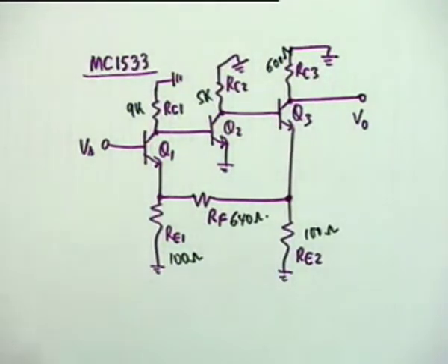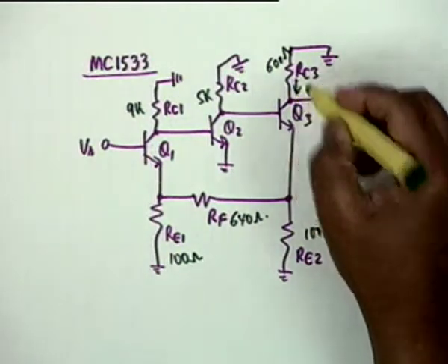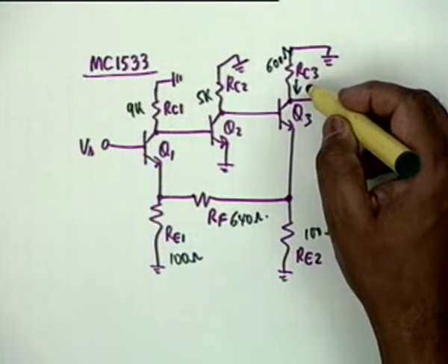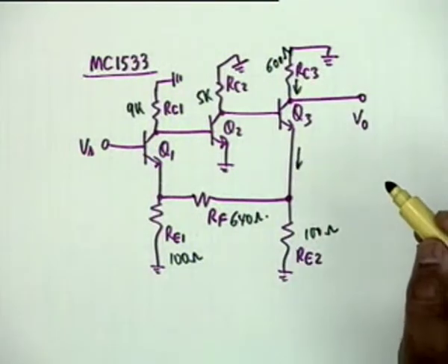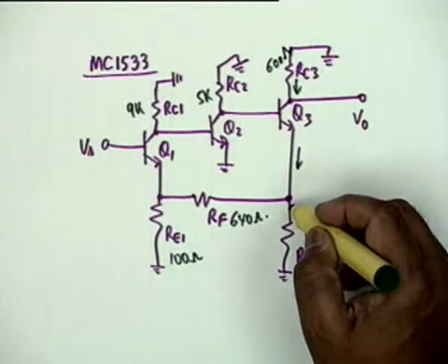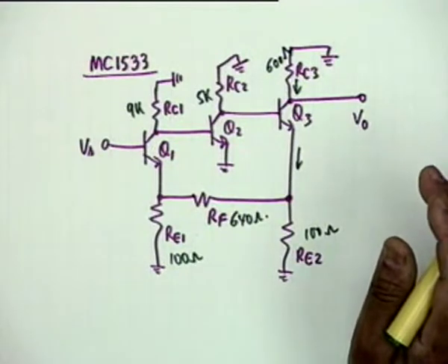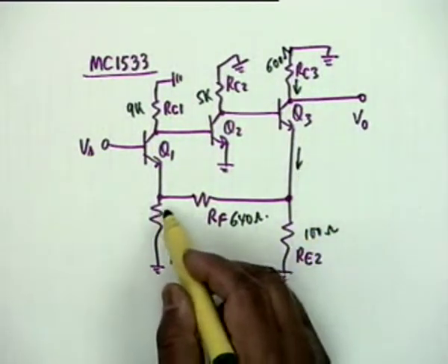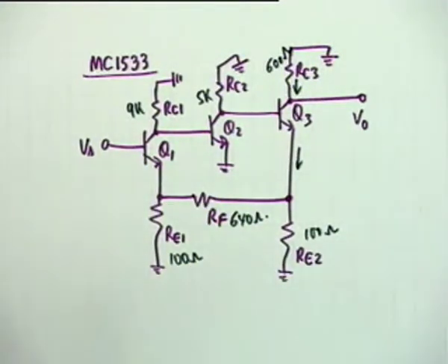Now, why am I saying that this is a series? You see the current here, the output current, approximately the same current flows here, and therefore this is a current sampling. Okay, this also we are acquainted with. This is a very standard method, particularly in IC configurations. So it's a current sampling, and obviously there is a voltage comparison, and therefore this is a series.